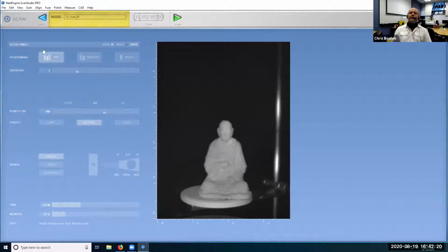Now, with this 360 paneling, we can call out how many panels we want to create, either by creating 4, so essentially at 90-degree increments, all the way up to 16. 16 would be capturing, every 20 degrees, a very, very comprehensive scan. Now that is probably overkill. And that also is alarming in terms of, if you notice down here, the time and the memory requirements based on the information that we're putting into the scan itself.